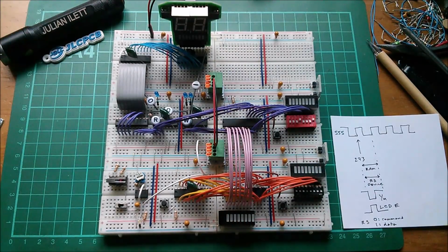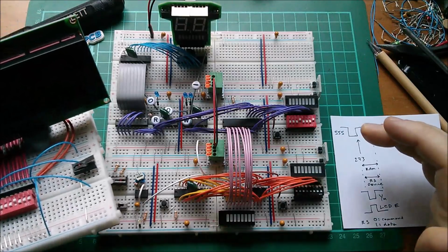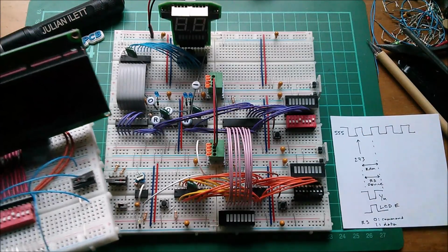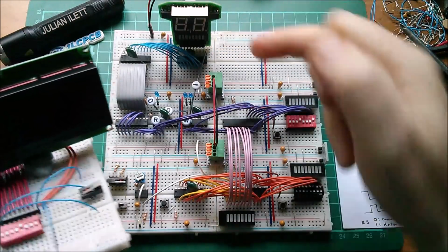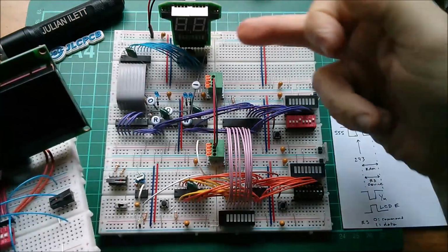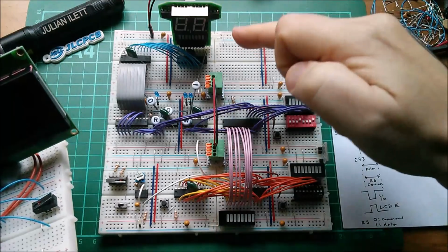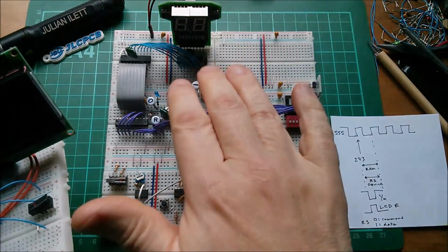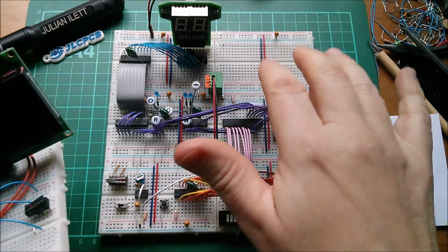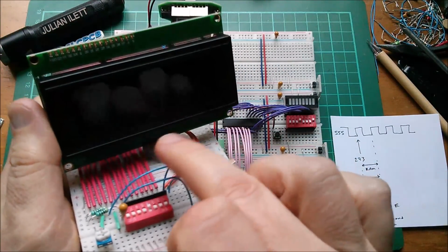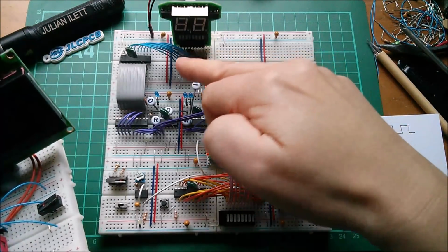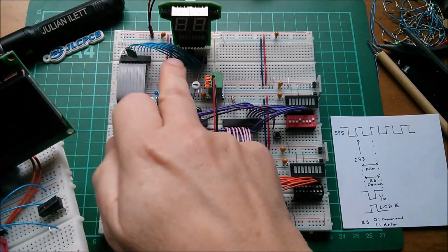Now really the issue here is one of timing. I don't really want to put all the data lines of this behind a latch and then all the control lines behind another latch, and then by using various patterns on the latches, set data, set control lines. What I want to do here is put the data lines straight on my data bus, which is these 8 blue wires here.